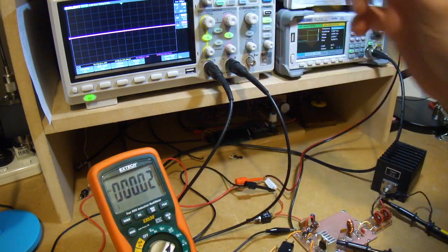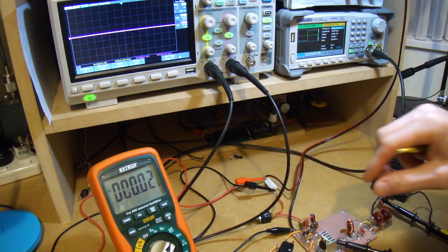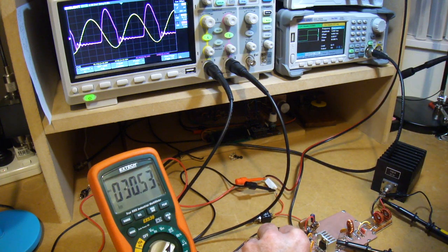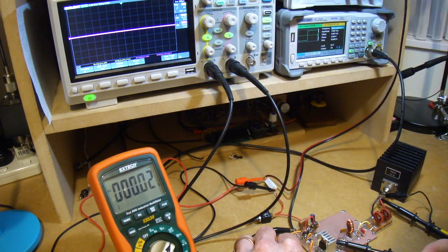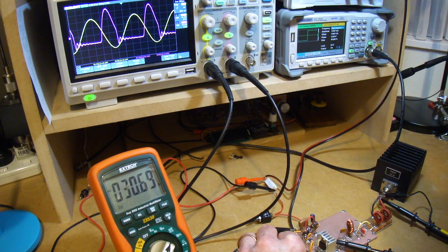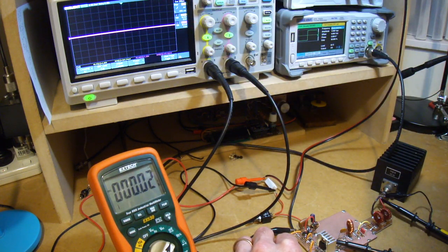So up on the scope there, let me just see, we've got 12 volts coming on in, and let's ramp that up. So we'll see two traces. We'll see the yellow trace, which is the voltage across the 50 ohm load, and the purple trace is the voltage across the MOSFET. I think that sort of sets the scene.